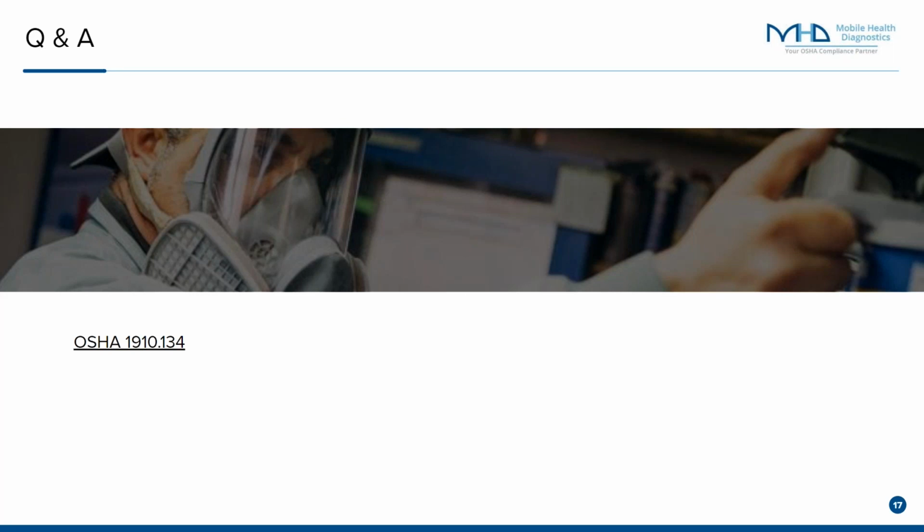A fit factor is calculated via an algorithm with the TSI PortaCount, and also via an algorithm for the OHD QuantiFit. I really couldn't go into the specifics of that, but if you have specific questions on how the actual number is calculated, I would reach out to the manufacturer and they can provide additional clarity. But if the number is exceeding the minimum, say we're testing a full face respirator and the fit factor comes back at 4,000 and the minimum is 500,